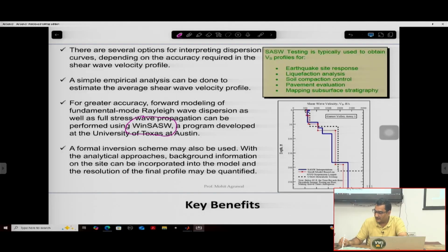So this is the model that you see. This is the model of shear wave velocity with respect to depth, and you can see the shear wave velocity varying with depth up to around 300 meters or feet. They have developed the model for this particular valley, Garner Valley, and for developing the model they are following some kind of inversion scheme.